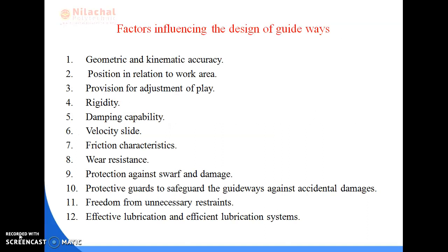Factors influencing the design of guideways, means which factors should be considered during the design of the guideways. First one is geometric and kinematic accuracy. The dimension of the guideways should be the correct one. The position in relation to the work area, means according to the work area, the position of the guideways should be a perfect one. Provision for adjustment of play.